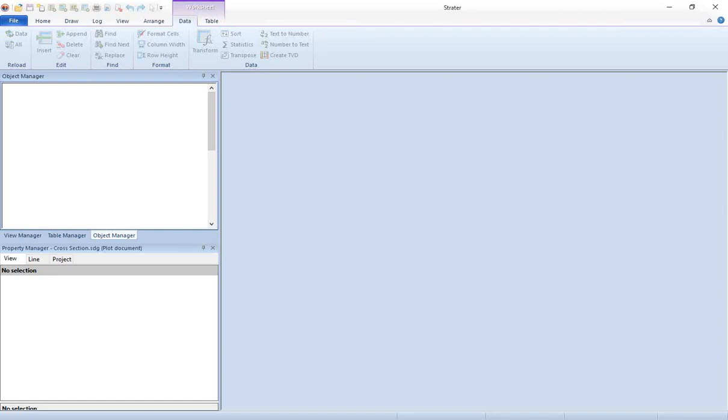So we ship Voxler with a number of pre-written scripts that are located in the samples directory. It would be a good practice to ensure that one of the scripts can run against Voxler before trying to export cross-sections from Strater into Voxler. So this is my pro tip number 1, is to make sure Voxler scripts can run before exporting cross-sections from Strater.